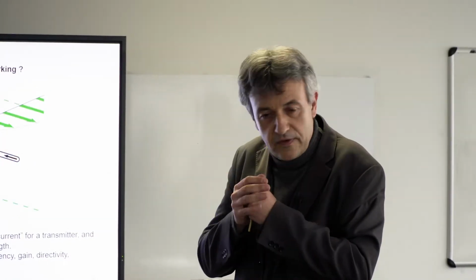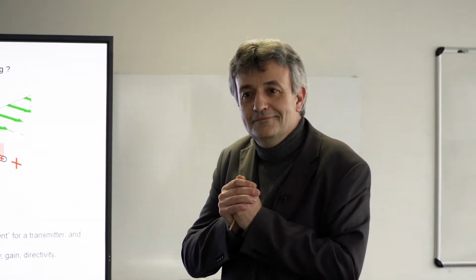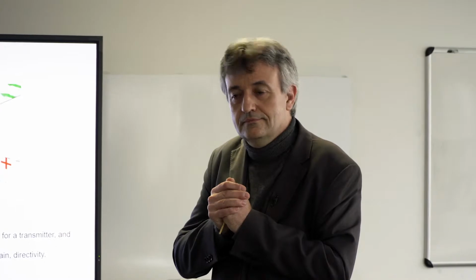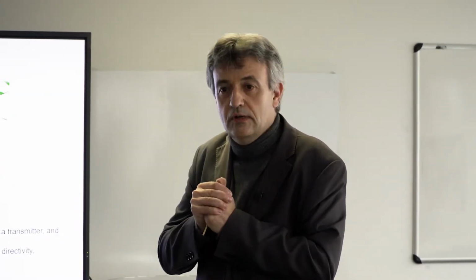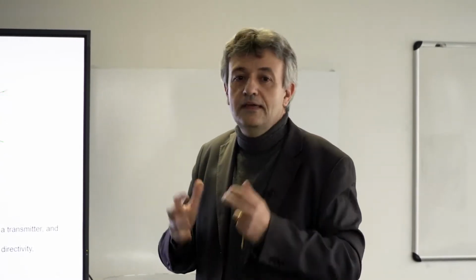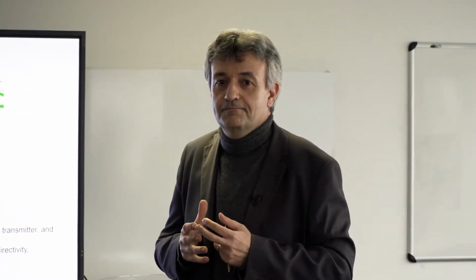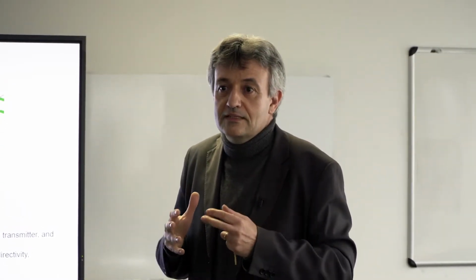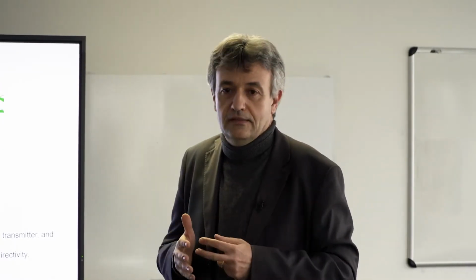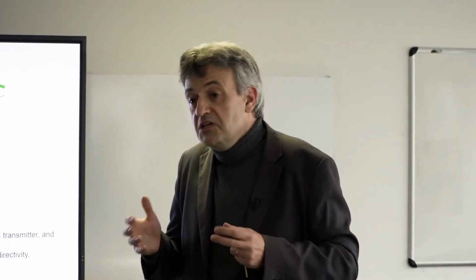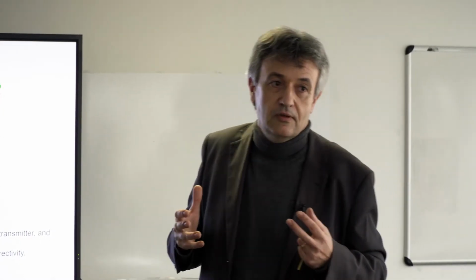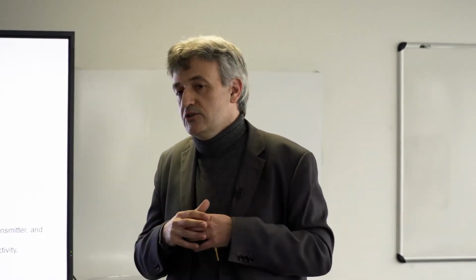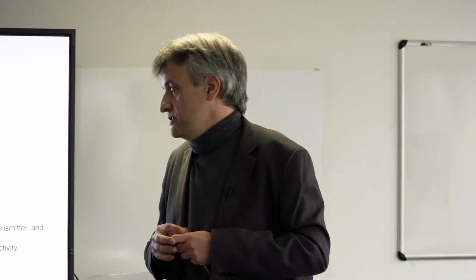Even if the antenna is very small compared to the wavelengths, there will be some drawbacks. We'll come back on that. But even if it's very small, there is something so that it's resonating. If you want to optimize it as much as possible, it has to resonate. If it does not resonate, you will have some radiation, but very, very small radiation as compared to what you could do with a resonant antenna.